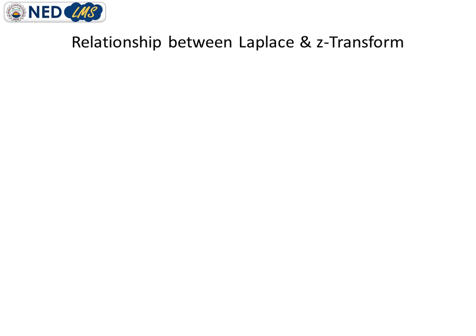As we are more familiar with the Laplace transform as well as its stability region and its pole zero constellation, we will try to transform all those concepts onto the Z transform. This way, we will learn how we can determine the stability and frequency response of any discrete time system. So first we have to analyze what is the relationship between Laplace transform and Z transform.